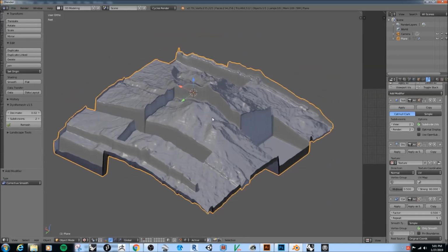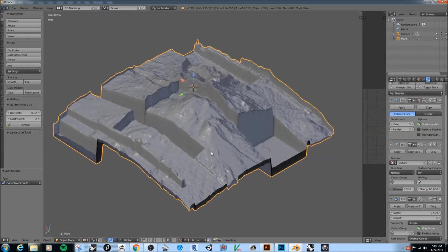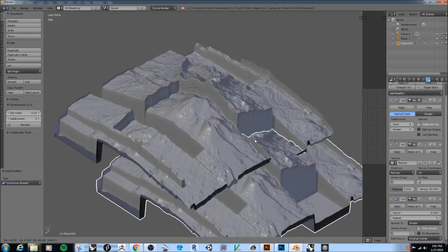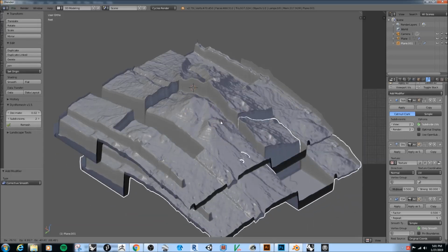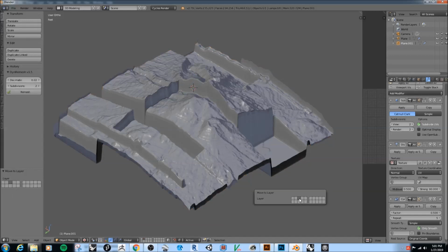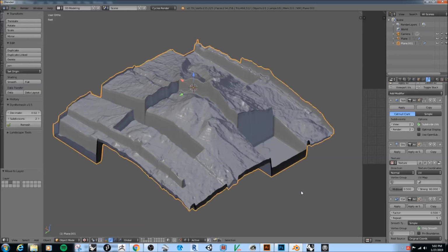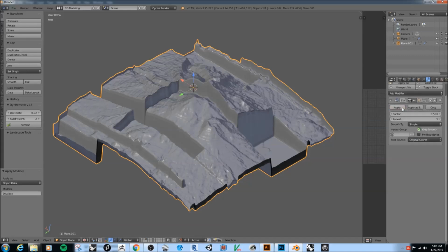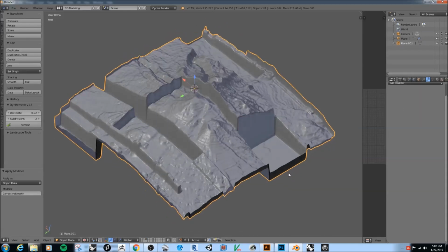Okay, so the first thing is, if you're going to do this, make sure to keep the original, because if I hit apply to all this, I can't go back. So the smart thing to do is you hit Shift D. That makes a copy of it. Now, as soon as you do that, it wants it to go somewhere. Just hit Escape. The copy, the duplicate, is what's selected. Then hit M, and we're going to move it to another layer. So just move it over to the next one. Okay, and then down here, you'll see this is that duplicate layer. And so once on the duplicate, we'll go ahead and apply all of these guys. There we go. Okay.